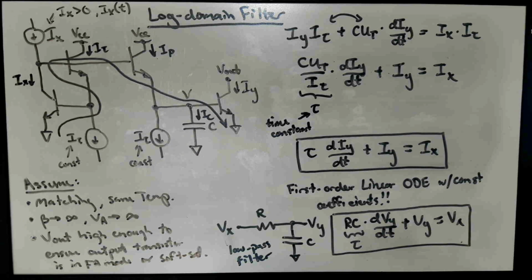Resistors are really big, unless you've got a very, very specialized process option which allows you to make reasonably small resistors. But most of the layers that you have available in an IC process are pretty conductive, and so to get a high resistance, you need to basically make a very, very thin wire of material snake back and forth, back and forth, back and forth.